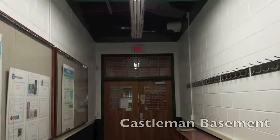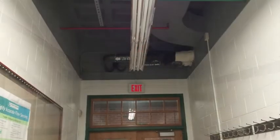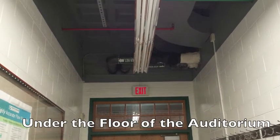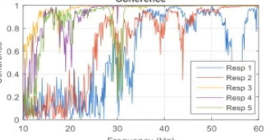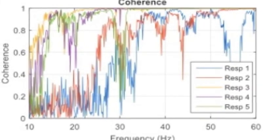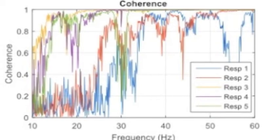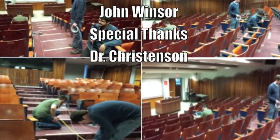The structure was challenging to measure because the stiff structure minimized response at several locations. We obtained the best measurements by measuring and exciting the structure near the peak of the modes. The coherence shows that we got good linear measurements over our valid frequency ranges, even though the structure was challenging to measure. This testing on the auditorium hall structure effectively illustrated the topics we learned in CE 5151.